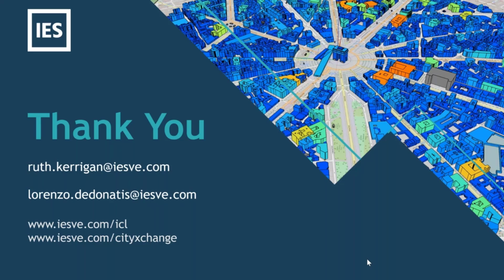And the answer could be there is a problem in the model, or it could be there is a problem in the building. So did they leave their lights on for a whole week? And that's also the potential of the dashboard, which will be able to show you live data from the energy meters, so that someone will understand that the lights are on not after a week, not after a month, but after 2 hours, 3 hours, or whenever they want to set up the alerts saying, actually, look, you have an energy model that is saying you're supposed to consume 100 kilowatt hours per meter square, and you're consuming 110, 120. So you can set up alarms after your actual meter is going too far from the simulated values. So that's the potential of it.